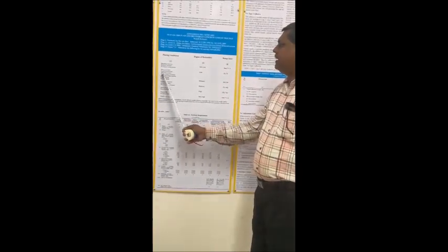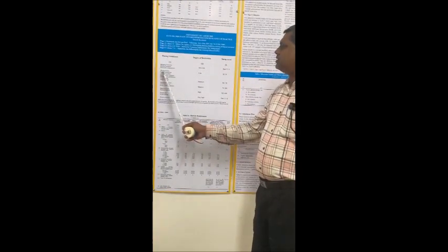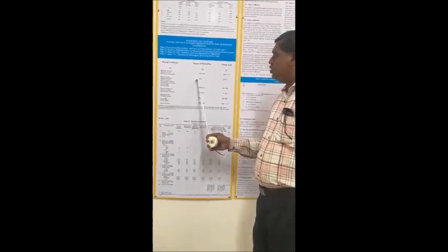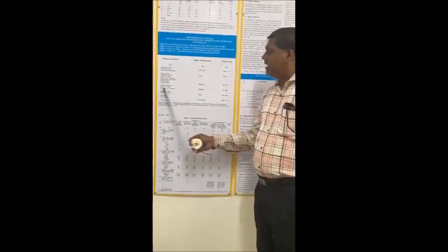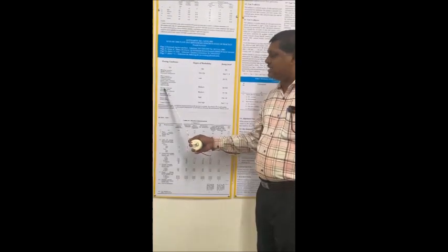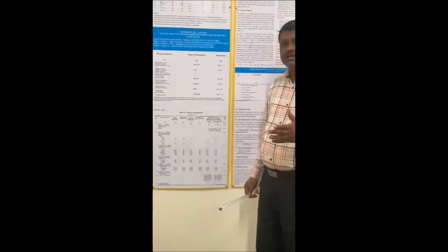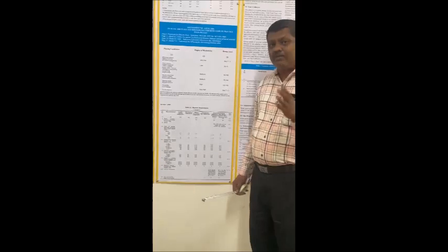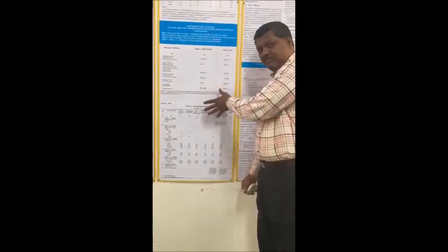Now second, different placing conditions are mentioned here: mass concrete, lightly reinforced sections, hand placed pavements, canal linings. The degree of workability is low and the slump required is 25 to 75 mm. Next, the third category is heavily reinforced sections in slabs, beams, walls, columns. Medium workability is required and the slump required is 50 to 100 mm. These things are specified in IS, and according to this IS, the concrete shall be prepared on site, and at the site the concrete workability must match this table of IS.